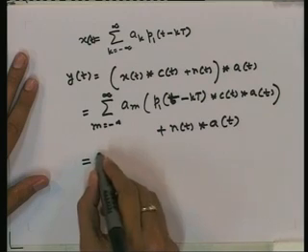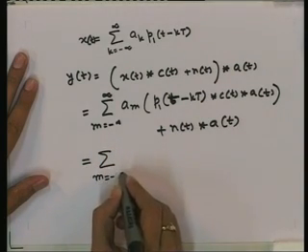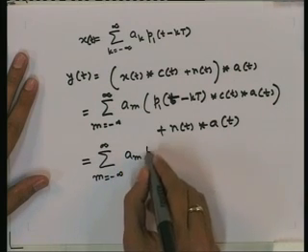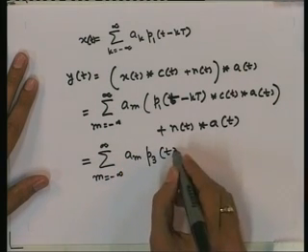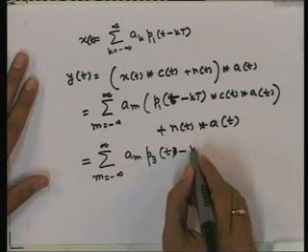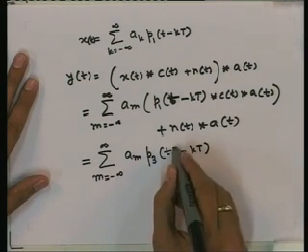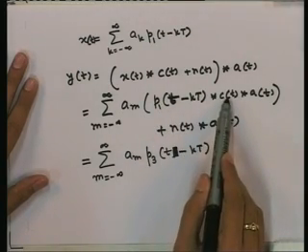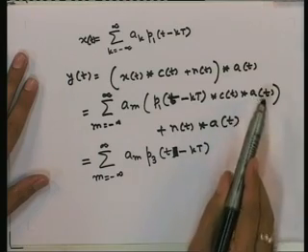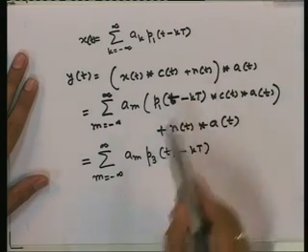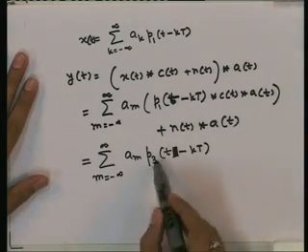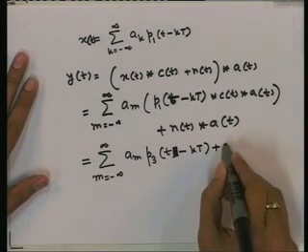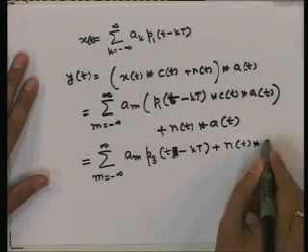So, this is equal to the sum of a_m P3(t minus mT). Remember P1(t) convolution C(t) is P2(t) and that convolution A(t) is P3(t). So when the input is shifted, the resulting output will also be shifted. So this is P3(t minus mT), and then the noise term remains N(t) convolution A(t).